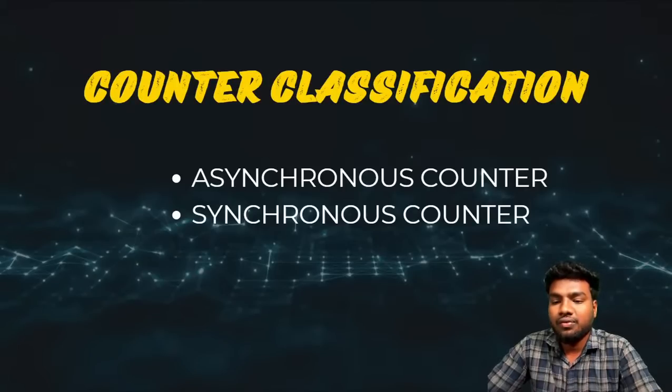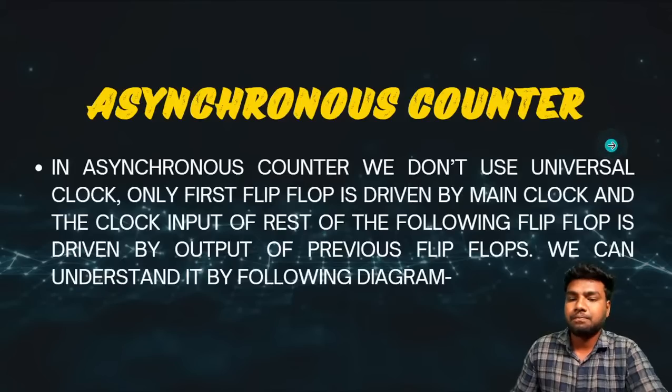In any asynchronous counter, only the first flip-flop uses the clock. The remaining ones, in a 4-bit counter, depend on the previous flip-flops. I will show it in the diagram.